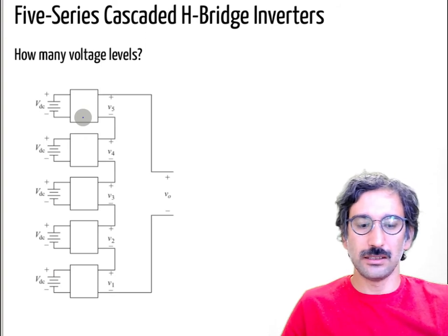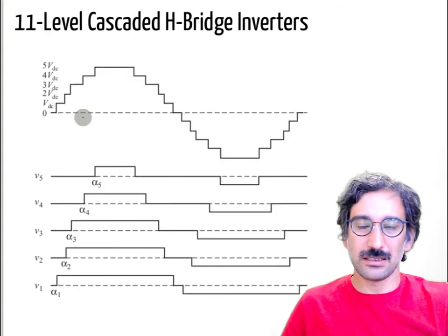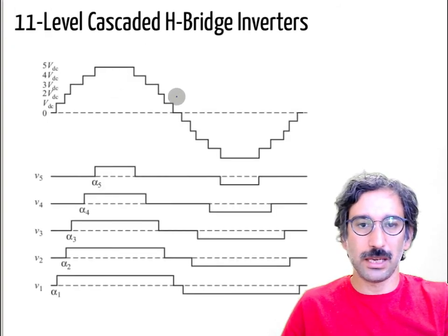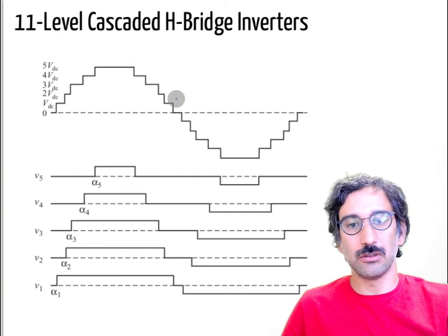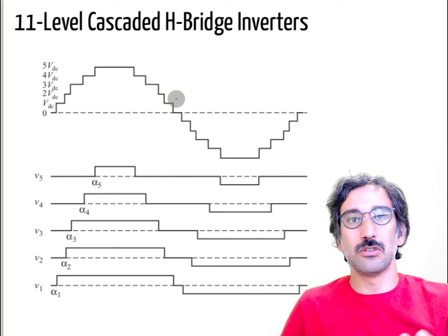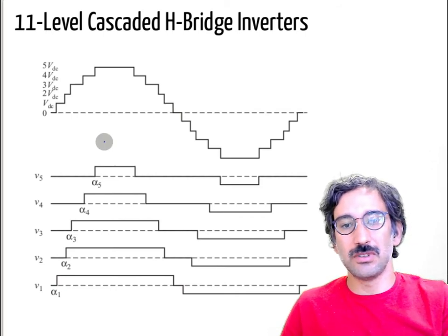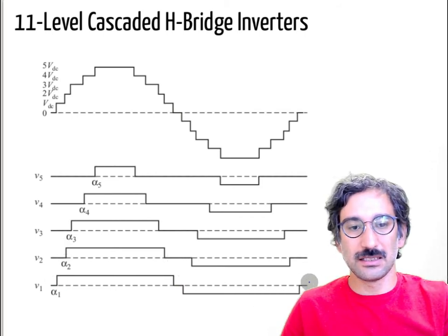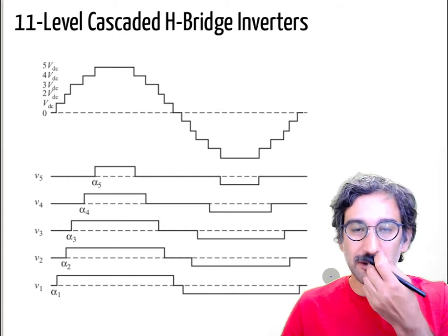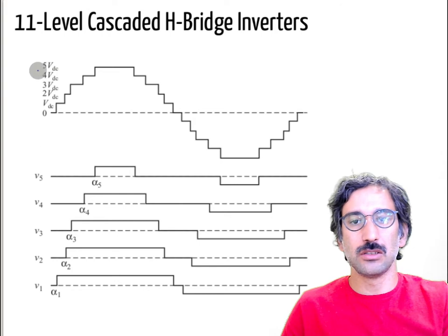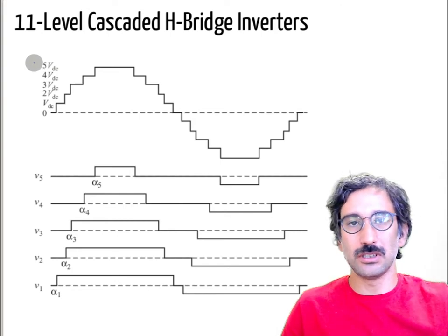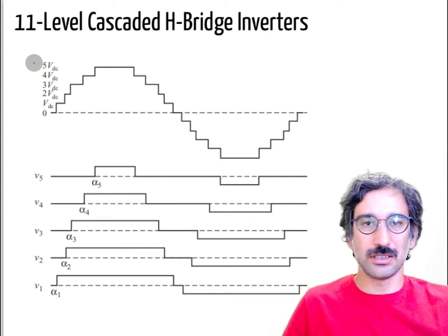Actually it has 2 advantages. Either you can make the voltage more sinusoidal, with less THD, or you can achieve your THD targets with less switching frequency, or you can use multi-level topologies to go to higher voltages with the available voltage ratings of your transistor switches.